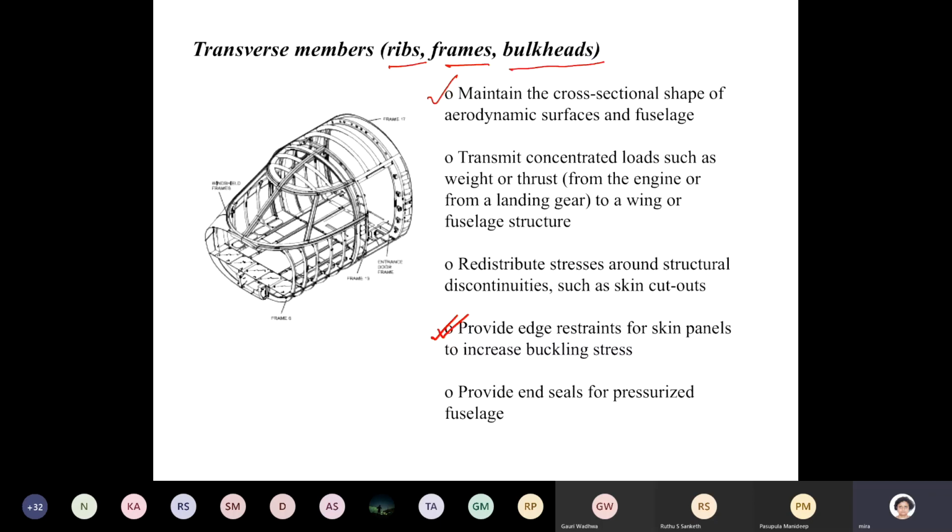The wood was first used to make a truss kind of structure, a two-force member truss, and later a semi-monocoque kind of structure where layers of wood were glued to each other to produce a monocoque structure. But there were several issues with this use of wood for aircraft construction.